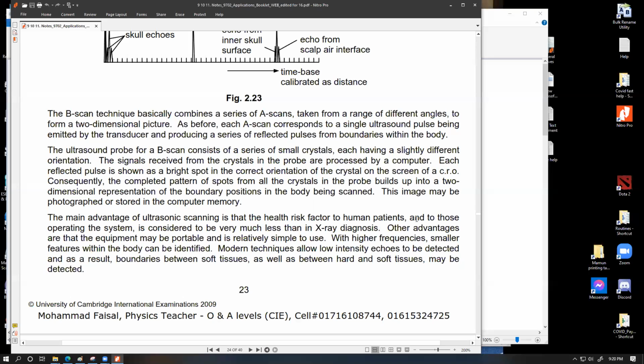Let's say the electronic component, which is responsible to measure the voltage across the piezoelectric crystal to be able to detect the individual pulses, has some latency. But if you use two different crystals, you can measure another pulse within that time. I mean, the time duration within which a crystal is getting ready for the second pulse, you might be able to make another scan with the B crystal, with the second crystal.